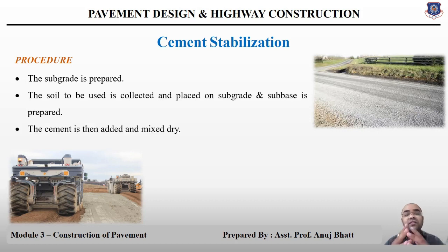Now, even with a well prepared soil, the cement must be mixed in as thoroughly as possible, otherwise, as it is generally used in low proportion, that is 5 to 14% of cement, it will not be evenly distributed.